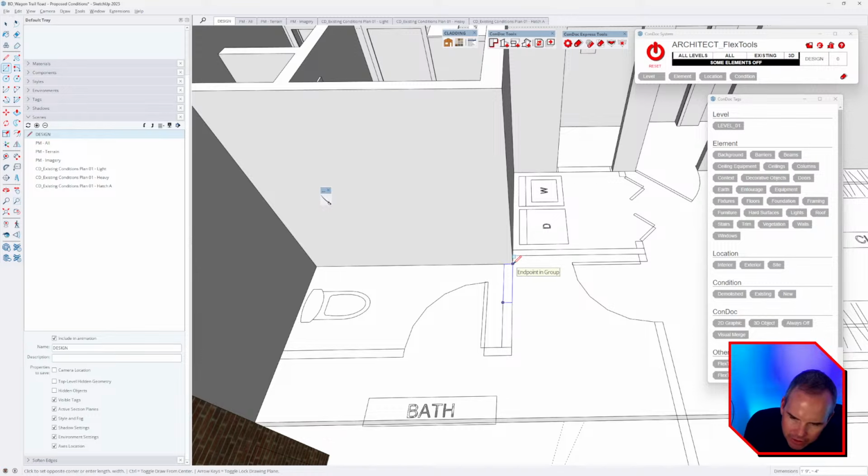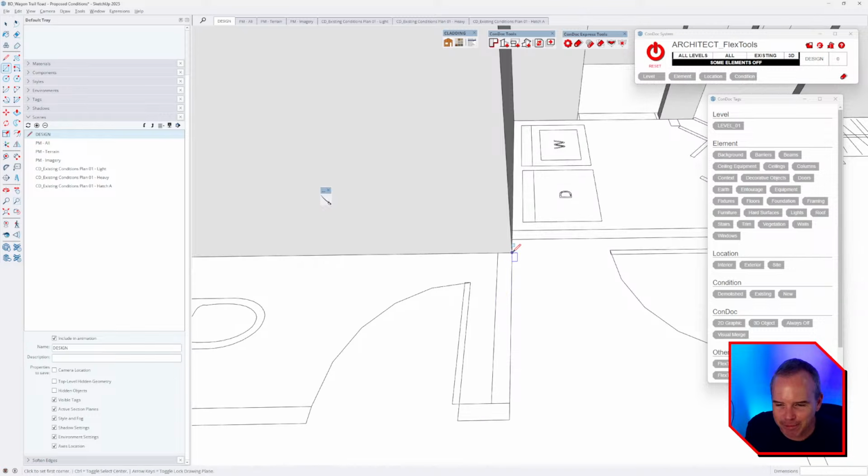And it looks like these walls in layout were drawn at 4 inches. Typically we'd want those to be the thickness of a stud. 4 inches is kind of nothing, right, John? If you're still listening. So I'm going to make this at 3.5, comma 3.5, enter.